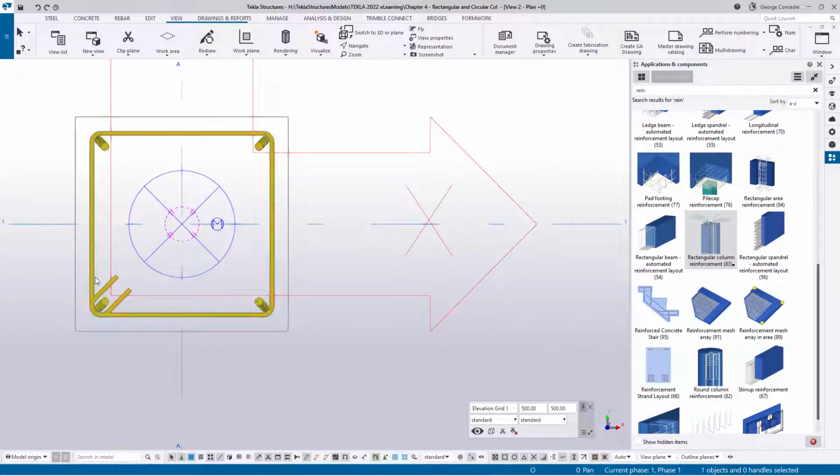What we want to do is start out with having a reinforcement in each one of the corners, but also having one in the mid of the stirrup, and then have a diagonal stirrup inside. I think that's what we're going to aim for.